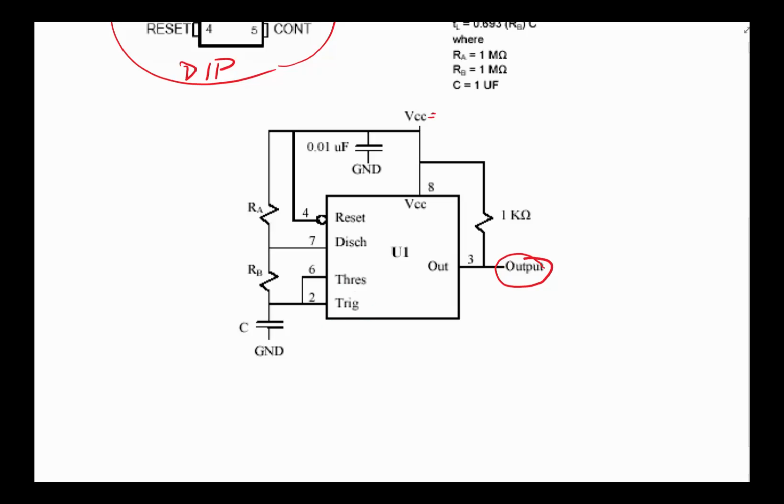There's really no input going into it other than power. So we're going to put in plus 5 volts here for VCC. Notice the VCC connections here are pretty obvious: 5 volts goes to pin 8, then to this capacitor that's connected to ground. This is commonly referred to as a decoupling capacitor, and its job is decoupling.